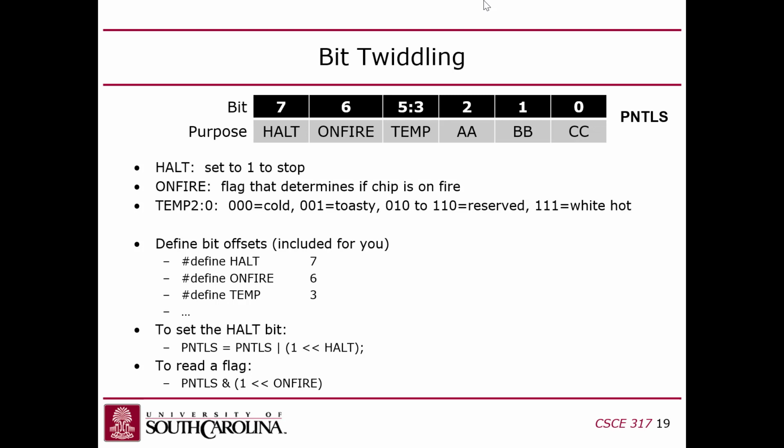it's when you start putting what Charles would call a magic number, meaning it's a constant that you put in your code, that it reduces the readability, because as you read it, you're like, well, why 7, right? It makes it hard to read. Also, if for whatever reason you wanted to change which bit was halt, like if you had another chip where halt was a different bit, it would be easy to change that if you just use the symbolic name for that.